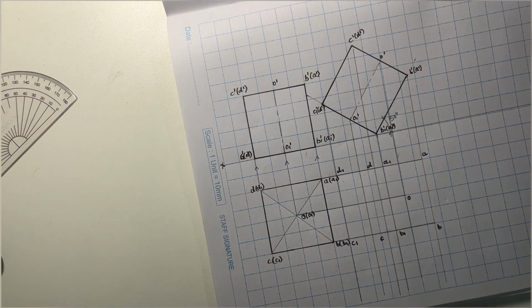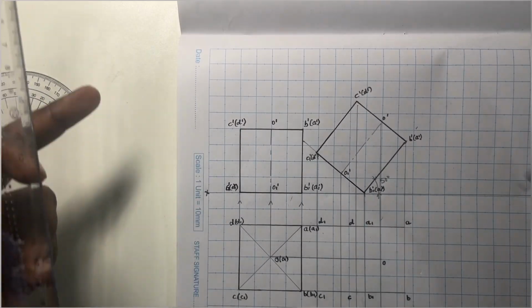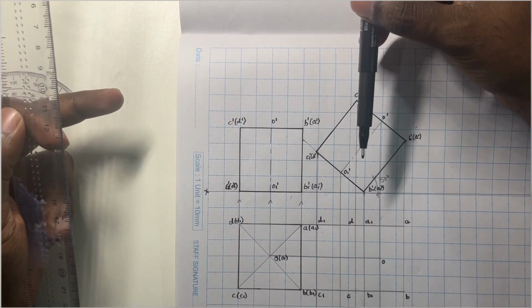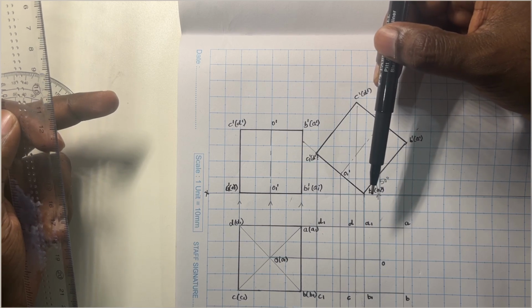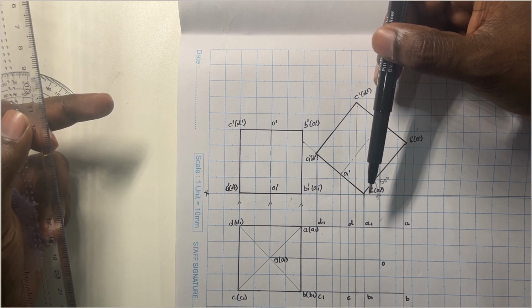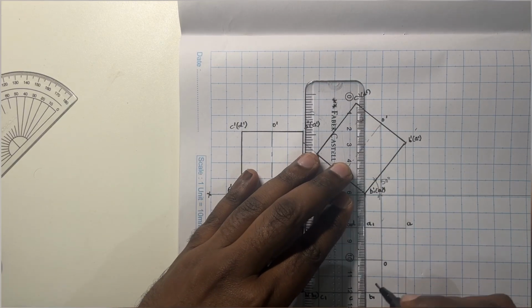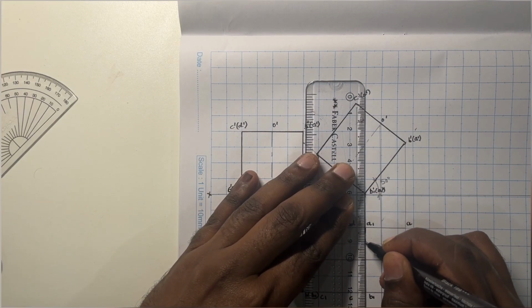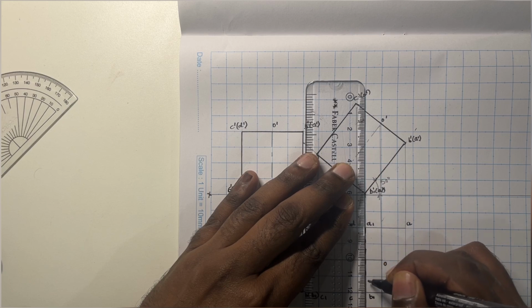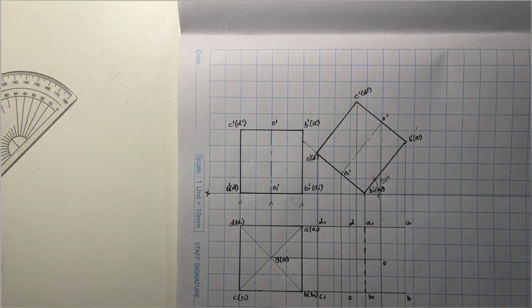So before we construct the outer edges, let us identify. The observer is going to look from this direction, and for the observer, the farthest corner points are B1 and A1. So all the edges emerging from these corners, that is B1 and A1, will be dotted. So let me complete this. So you can just see that the edge A1 to B1 is represented using a dotted line like this, and the other edges will be completely visible.